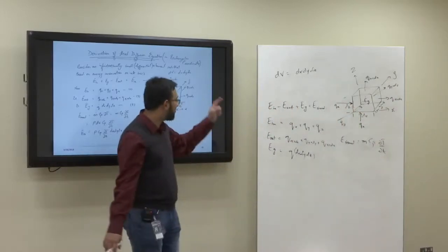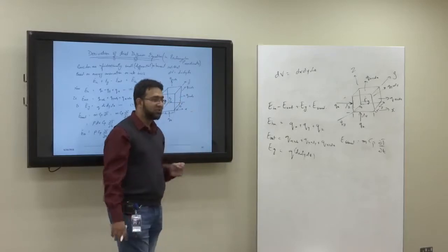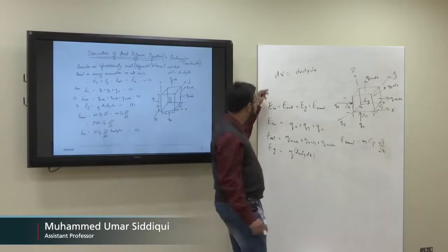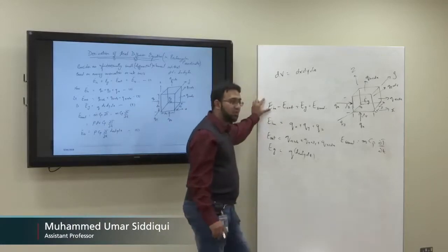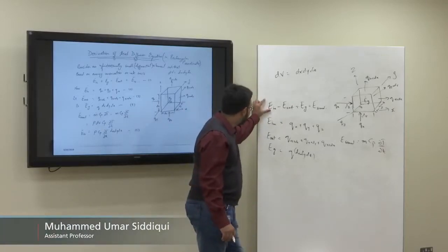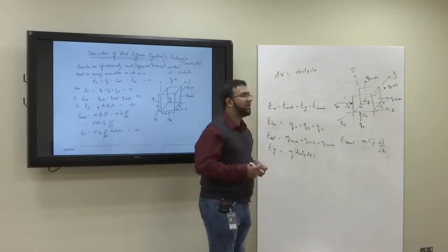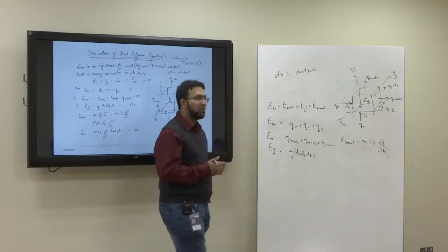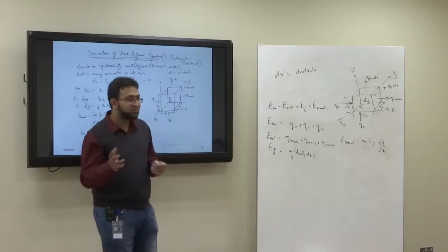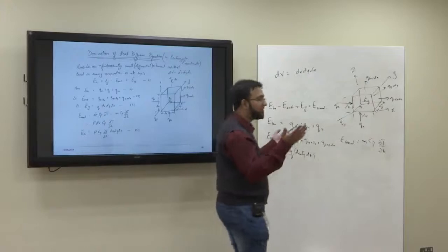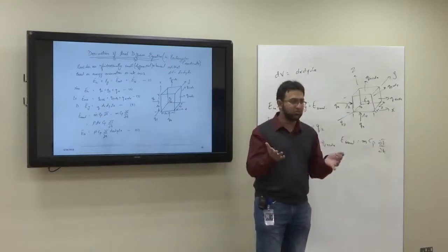So we have energy stored, energy in, energy out, and energy generated. We can substitute all these values in this main equation, right? Now there is one thing, Qx is heat flow, because we are considering the case of conduction. This is the heat diffusion equation, the conduction equation.